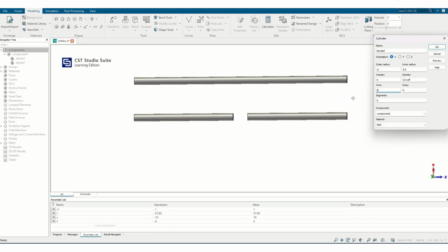and x minimum and x maximum. So I'm going to create it here. The distance of separation between these two is s. So I'm going to take the value in the middle, that is s by 2. I'm going to give it a small dimension like s by 2 minus 0.2, and s by 2 plus 0.2. Why I have chosen s by 2 is I have to select the center point, because the distance of separation between these two is s. That is why this.